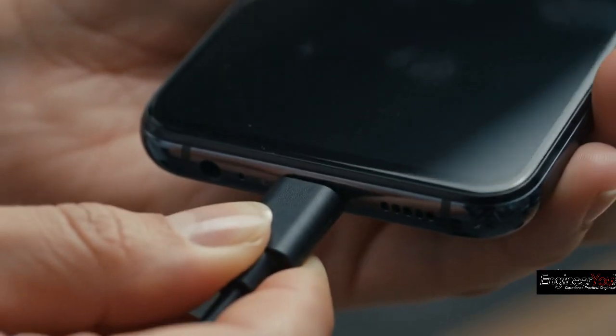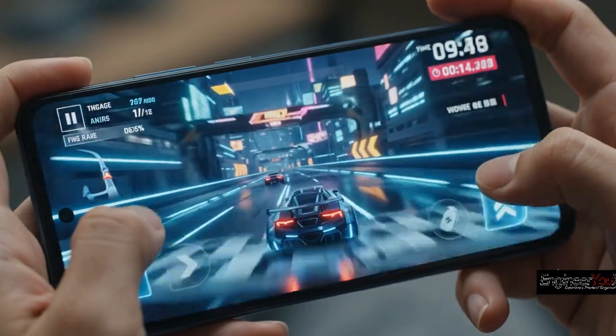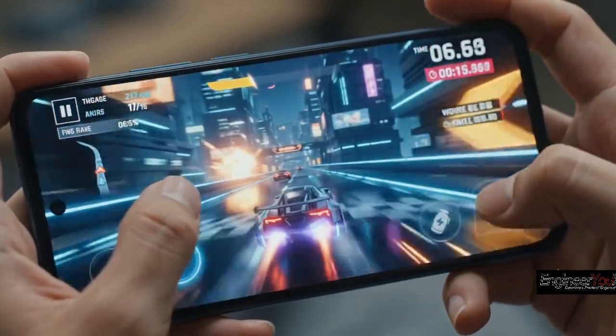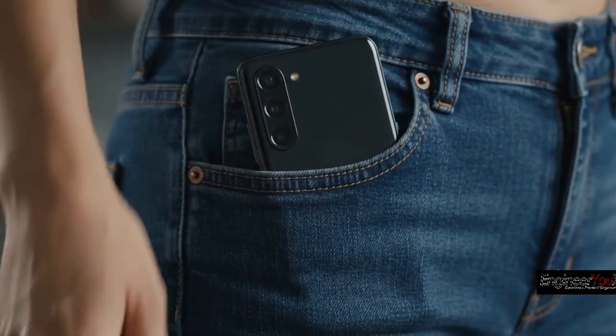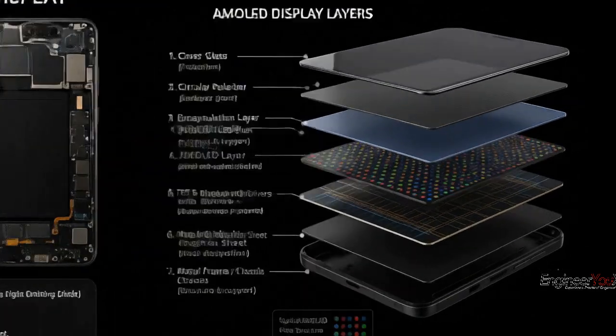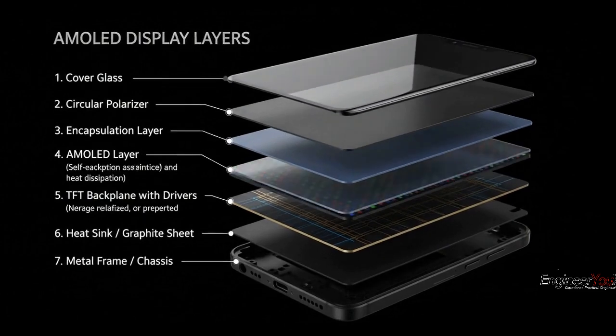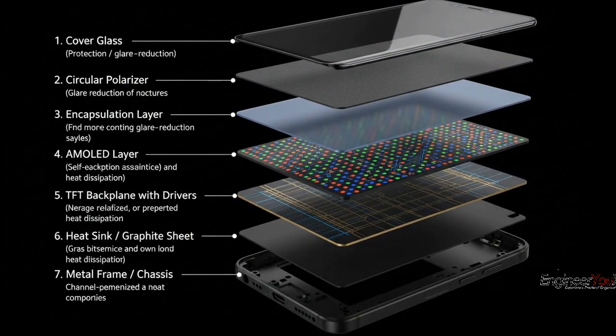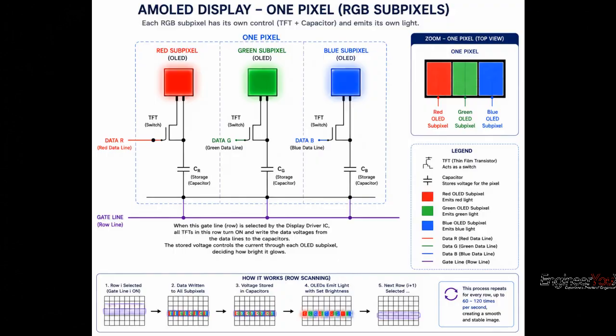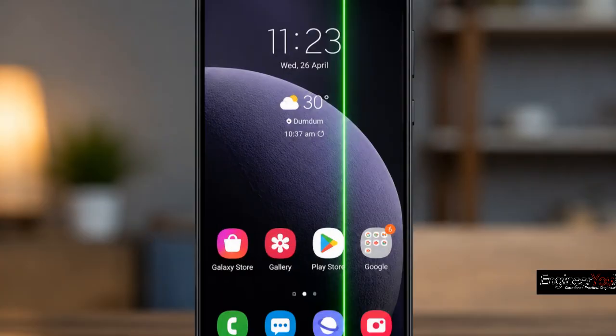Over time, repeated heating and cooling, mechanical stress, manufacturing defects, or physical damage can weaken an AMOLED display's driving circuitry. If the TFT backplane, column driver, or the bonding between the driver IC and the display develops a fault, the signal path for one color channel in an entire column can become corrupted. If the green channel is affected, all the green OLED subpixels in that column receive incorrect signals, creating a bright